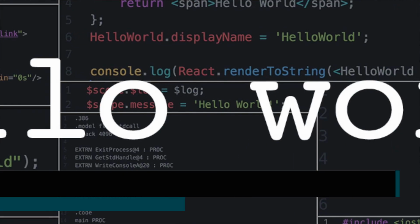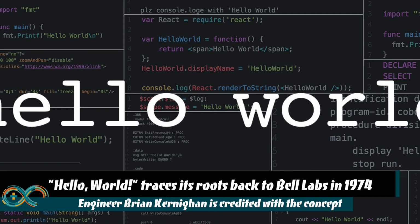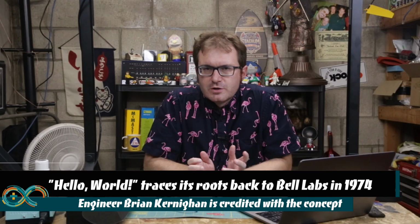So anytime that you're learning a new programming language or a new piece of hardware, you always want to start with what is known as a hello world type script. These are very simple scripts to let you know you've kind of got the basics of the structure working. Now on the Arduino, that is pretty much just having the built-in LED blinking. It's an on-off simple digital switch. We're going to take that one step further by controlling an external LED.